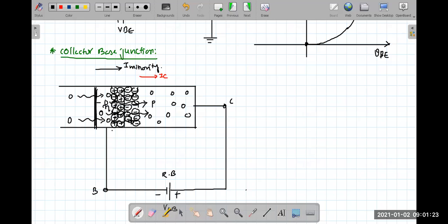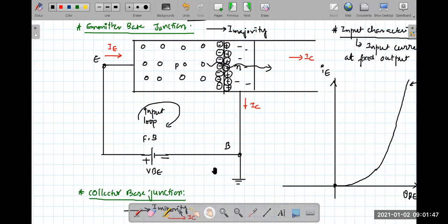Ayush, in fact, we have discussed the goal in the starting itself. If you are sending 100 charges, then we want more than 98% of them to reach the collector. So that's why we are making sure that all the charges are reaching the collector. Because if I leave it under no bias condition, there are very high chances that this current will flow towards the base.